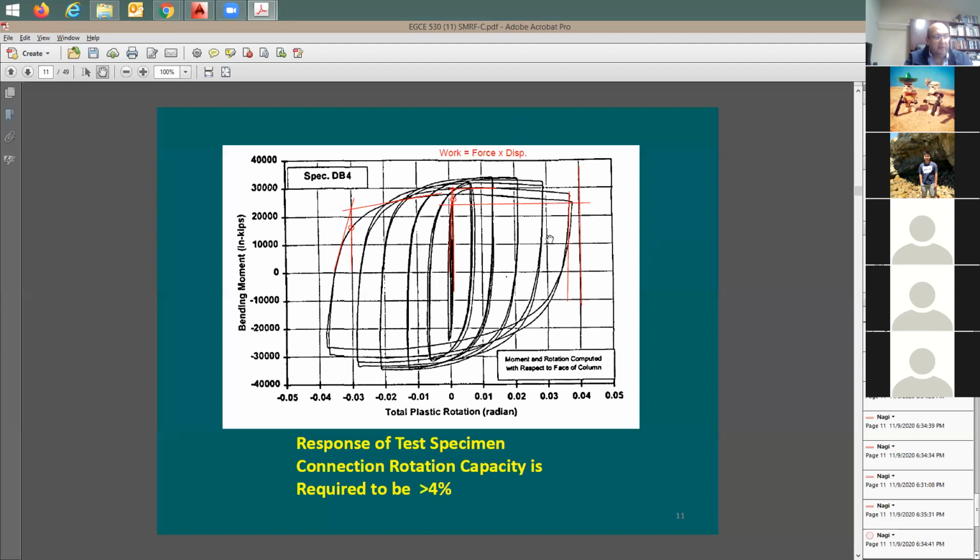So I should be able to find out this area here, and this area would be representative of the work in terms of the force unit and displacement unit. And once I do it here, right, I can have the amount of energy that I dissipated during that cycle. So I can really compare between two systems by testing them and looking at the contained area, if you like.